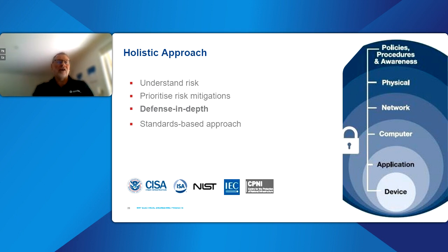You don't leave Studio 5000 logged in and open in the substation; you have auto timeouts enabled, so it times out. Your network is running, you've set up MAC lists and access control lists, et cetera, up the onion. So if someone breaches one level of your defense system, they hit the next. But CIP security ultimately is about the last level of defense.